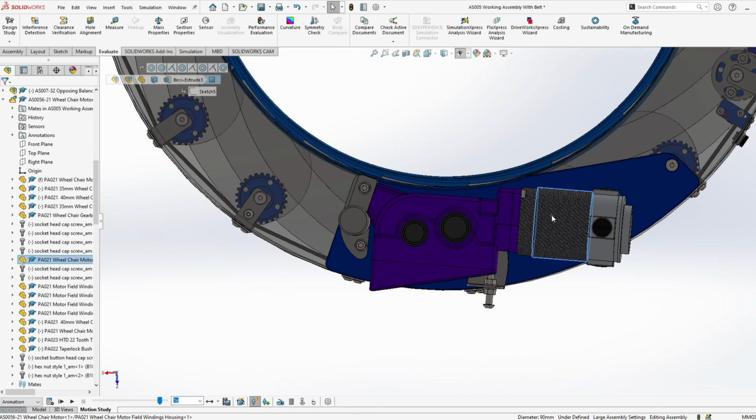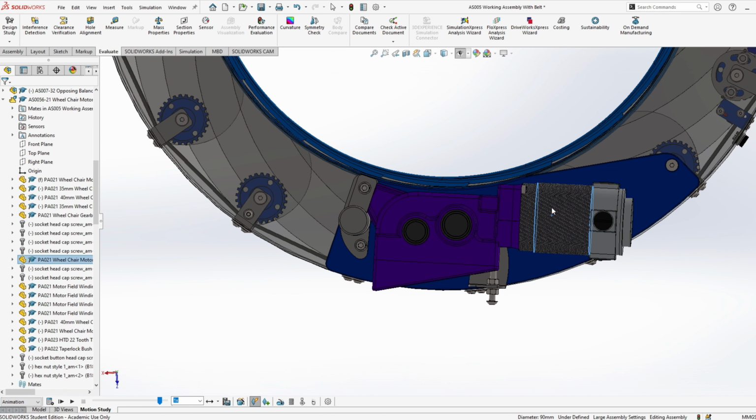Okay, so if I grab the motor at this point and move it inwards towards the center of the aperture and outwards towards the outside of the enclosure, we can see this bracket gliding on the anodized platform. We can also see the bollard type bracket to the left of it supporting the gearbox motor, whilst also allowing it to hinge and pivot.